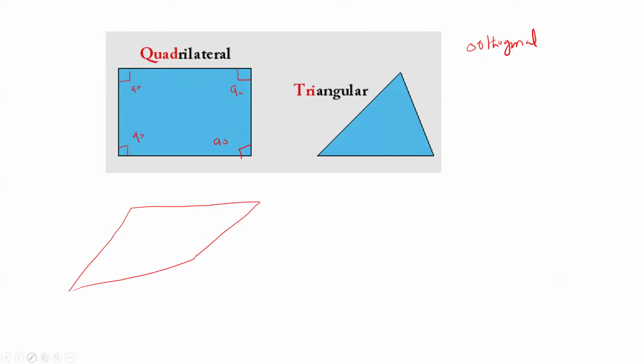So this quality metric, orthogonal quality, contains a lot of information: its angle and also its connection with the neighboring cells. I will go through all these things. Okay, one thing is the orthogonal quality. So its zero value is the worst, and one is the best.